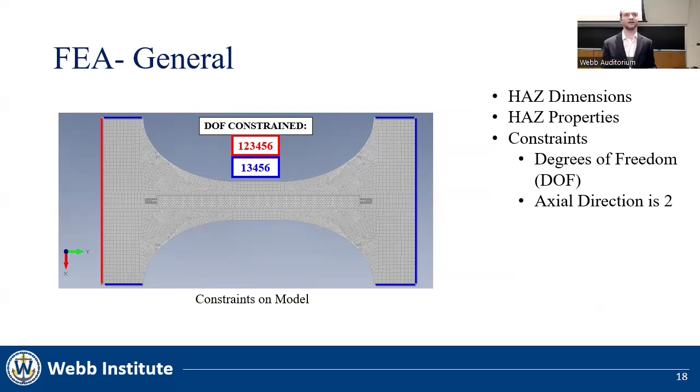Even though the real model is clamped in the areas enveloped by these constraints, they are deemed adequate because, for one, the used constraints have a significantly larger cross-sectional area in comparison to the center of the sample. And two, we did not want to have a constraint very close to the end of the stiffener because that could affect the simulation's calculation of that stress concentration. For loading, a force was evenly distributed on the side that was free to translate.